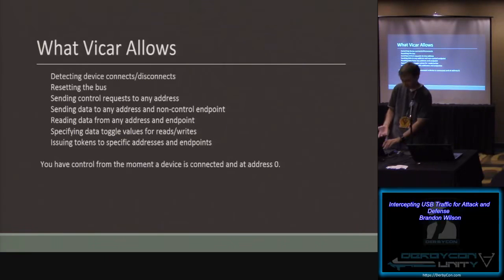It might sound kind of tedious, and it is, but it gives you the ability to handle weird scenarios, such as a peripheral suddenly switching to another address without your say-so. It also gives you the ability to handle multiple devices. So, if you plug a hub into the USB host shield, then it also becomes your responsibility, if you choose, to respond to any new device connected on port events from the hub. So it's not limited to a single device. You can do anything you want to over USB through this thing.